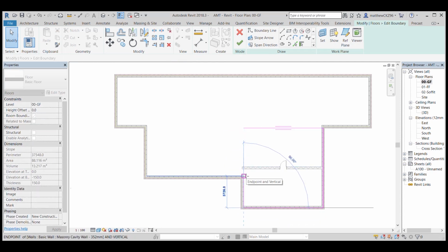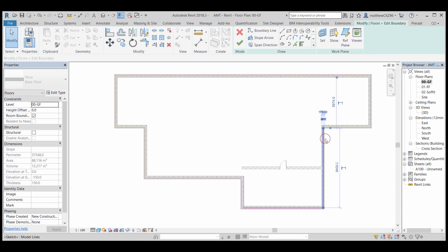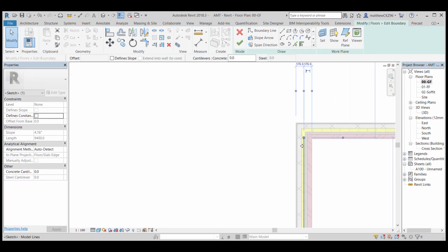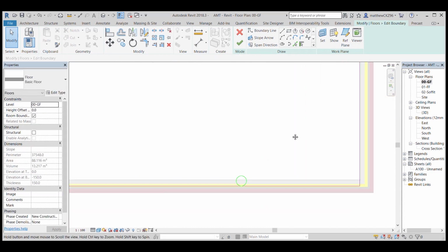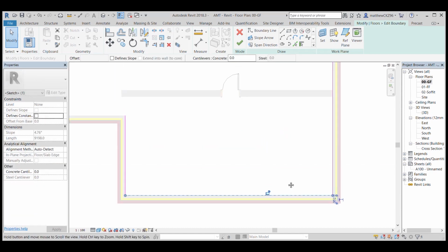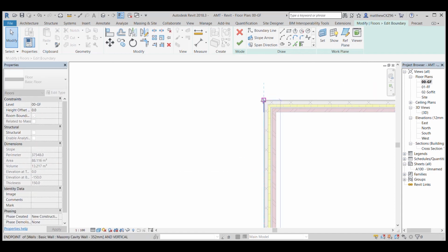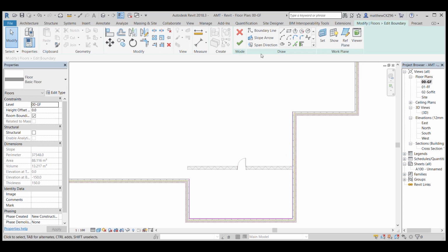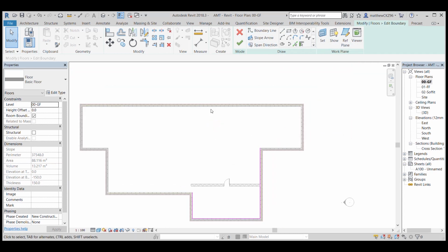You notice at the corner, the endpoint, when you get that purple block. Delete this line, select it once, delete, and then this line, if we notice it's over the wall a little bit, if we just drag it to just the edge for now, that's fine. The plasterboard. Same here, click that. Click and hold, drag to the blue line. It will snap as well, you'll feel it snap. Drag that blue dot to the corner. Right. We then want to add more lines to complete the floor's interior.